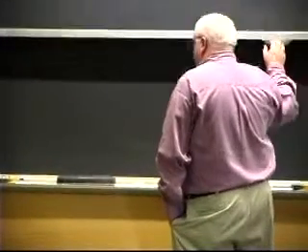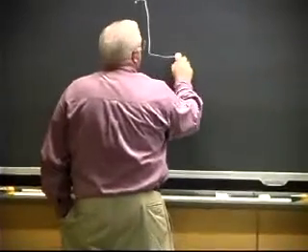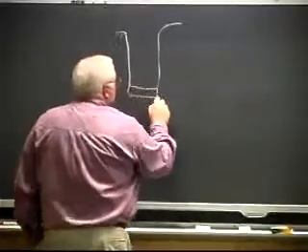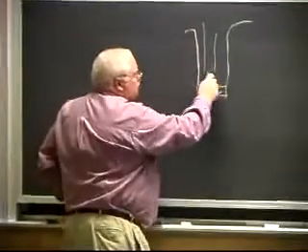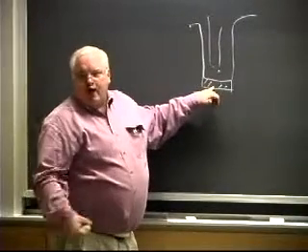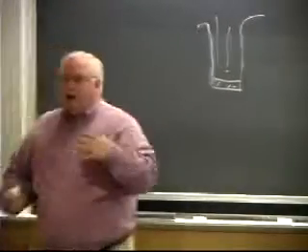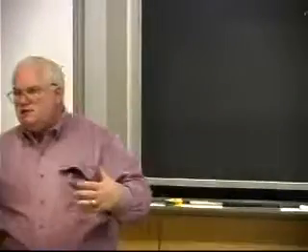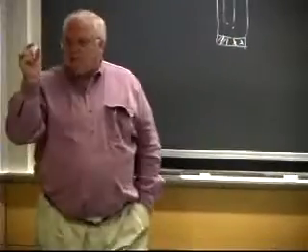Now, they quit doing it for a number of years, but what happens is I'm going to actually have the hole started in the rock, and this little layer right here of rock at the bottom of the hole, and I've got a jet burner shooting in here with 2,000 watts per square centimeter. With a typical thermal conductivity of granite or something like that, it turns out that I'm going to heat up just a 1 or 2 millimeter layer and it's going to expand. And if it expands, what happens to a brittle ceramic? It's going to crack. And so this little layer right beneath at the bottom of the hole will crack up into a bunch of little pieces, form small little cracks.